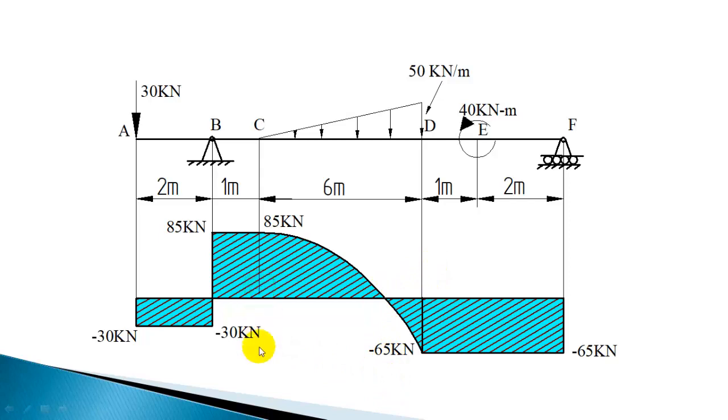We know the bending moment at C and at D, but between C and D you are going to get a peak corresponding to the point where shear force is 0. Wherever shear force is 0 under a UVL or UDL, you are going to get a peak, and the bending moment curve will have a slope of 0.